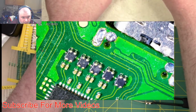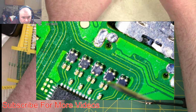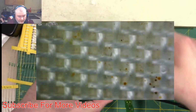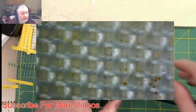So that is another use of an inductor. They're using a capacitor to filter out some noise, and then they're using these inductor filters, these EMI filters, to filter out any spikes or changes in current on a video signal, to clean it up. So that is some of the basic common uses of an inductor.